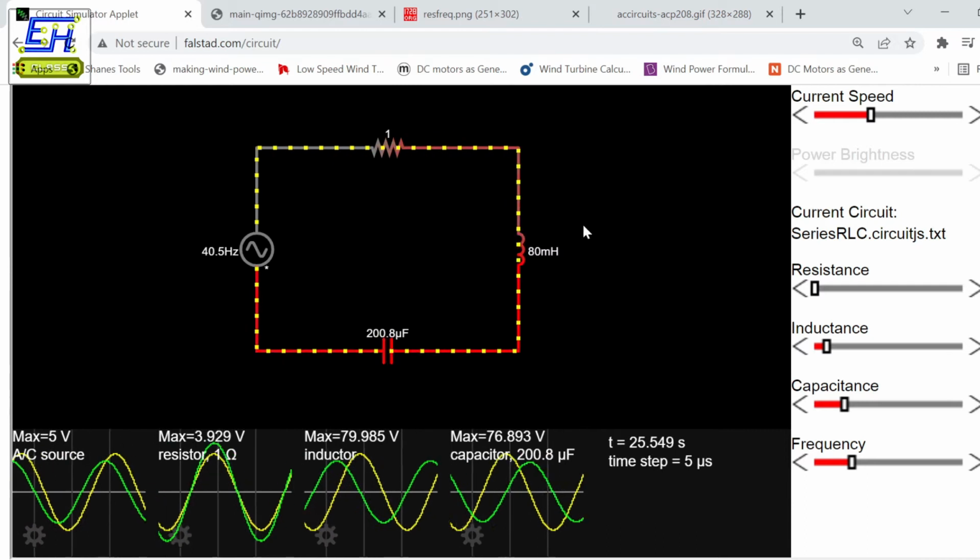This circuit is also known as a tuned circuit and an acceptor circuit, because it can reject all other frequencies. The radio spectrum is so huge and you want to tune to a particular frequency in the radio headset, so you definitely have to only accept the frequency that you want to listen to. You can simply select your components accordingly. You can vary these components, and accordingly change this maxima around this frequency to select a particular frequency that you want. But notice that this acceptor circuit is not perfect.